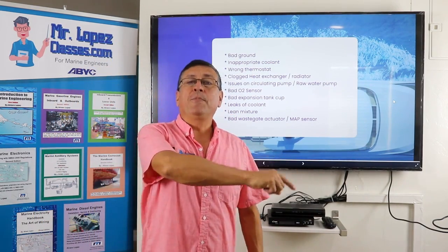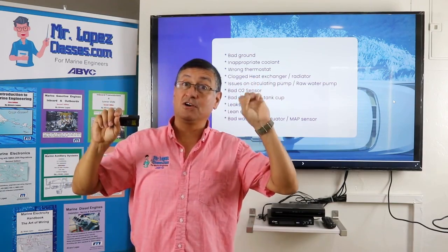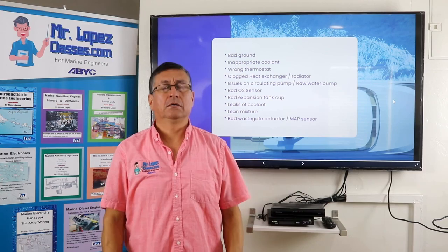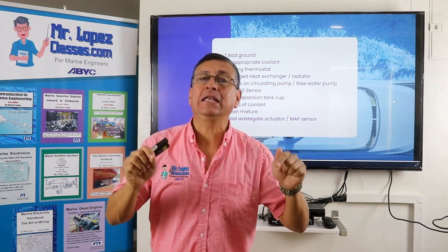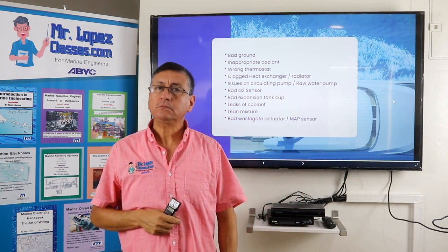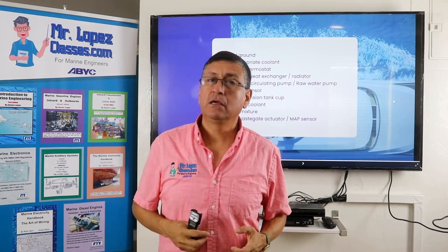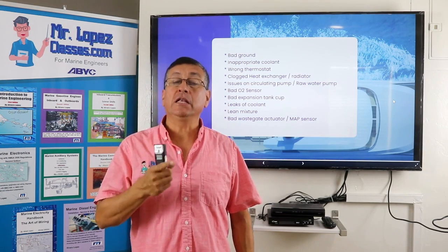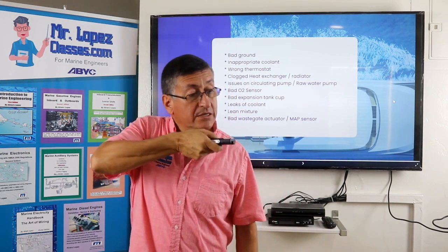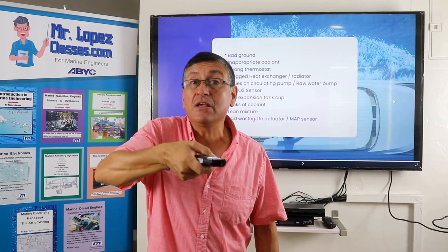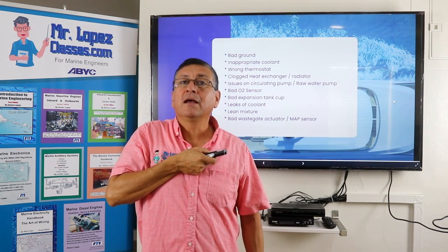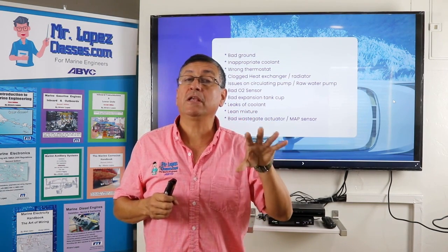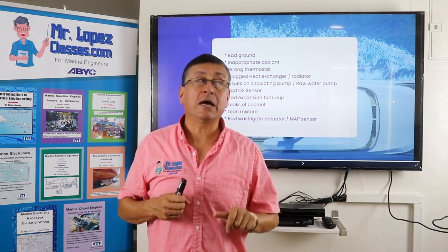Another very common possibility for the coolant temperature sensor code being activated is that the mixture is lean. The mixture is lean, not rich, lean. I have more oxygen and less fuel. I recommend using the temperature laser gun to check in what cylinder the problem is and isolate the problem. Probably in that cylinder the injector is opening improperly or the injector is damaged.